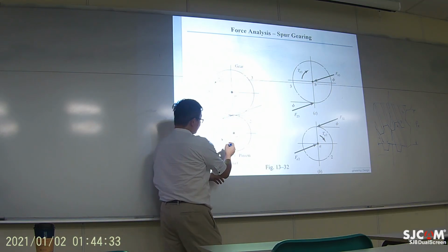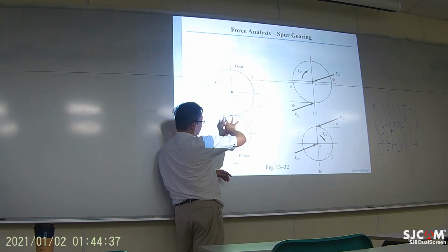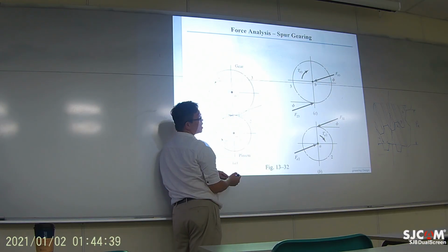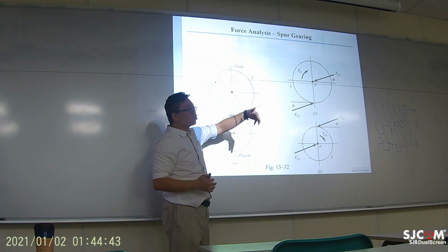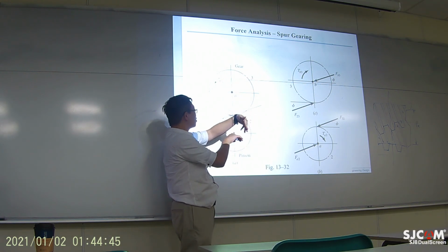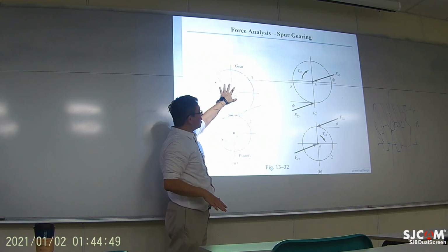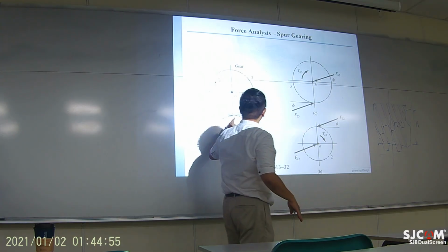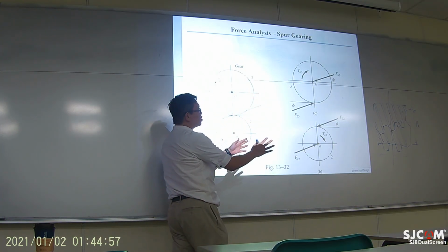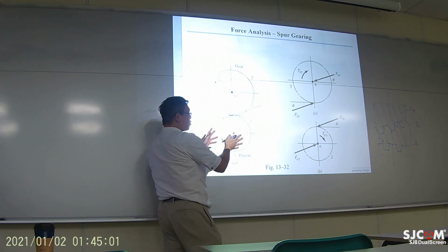And since I am rotating the pinion clockwise, the other side is resisting my rotation, so definitely I'm pushing it. If I stay on the big gear, I know there is a force pushing me along this pressure angle. This is how you determine the direction of the force.